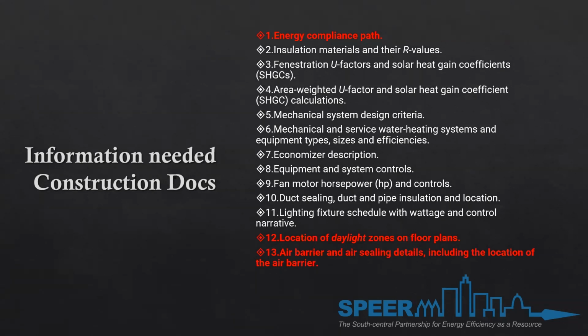At the very bottom, we've got location of daylight zones now needs to be on the floor plan. And now in the 2021, daylight zones are broken into top light and side light zones, making up the daylight zones, and the percentage and square foot of each one needs to be listed in detail on the plans.